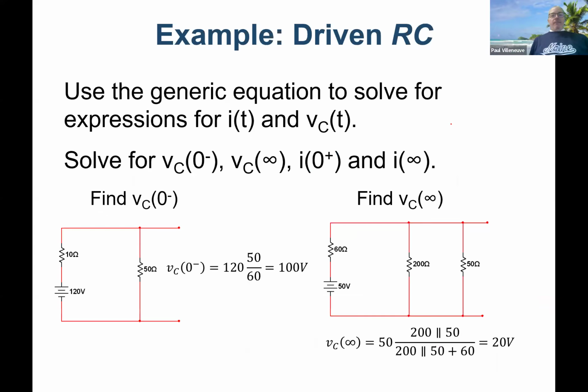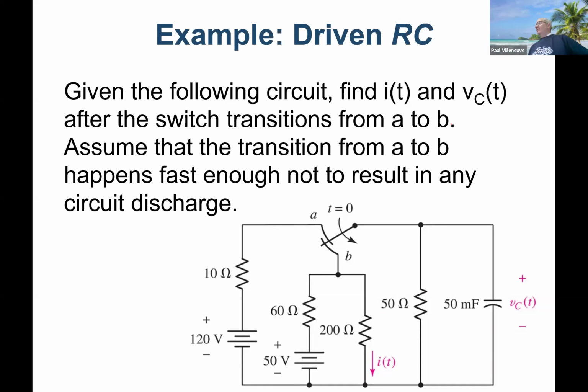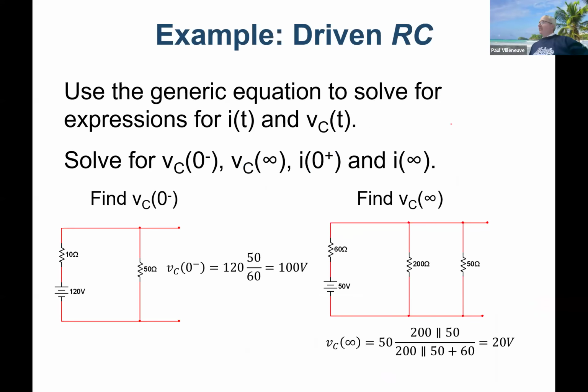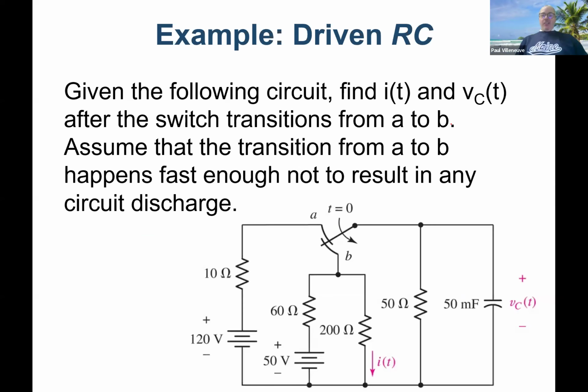Okay. All right, everybody understand what we're doing? All right. Let's build the circuit in position A. This is what the circuit looks like. What happened to my capacitor? Capacitor's not there. You can see it here, but why isn't it in this circuit? It's fully charged, so what does that mean? It's an open circuit. So I don't have to show the capacitor when I'm calculating the initial condition voltage, do I? Because it's fully charged, so there's nothing going to it.